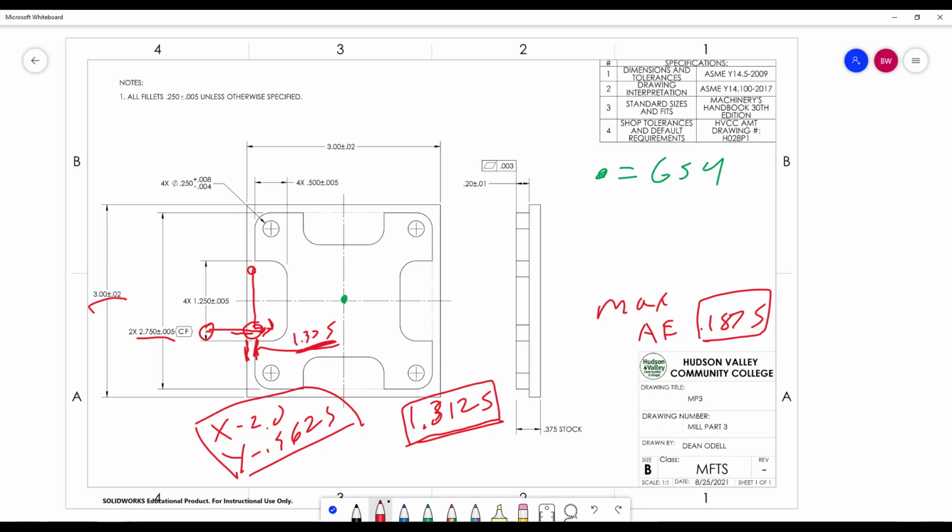Okay, now this 0.5625 number is the wall we want to create. We want to stay a 1/16 away. Okay, so we don't necessarily want to go here. We're going to create this with the lead-ins, with the cutter comp.